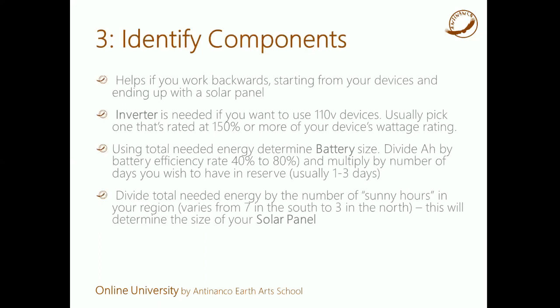Then we're going to figure out how many sunny hours we have in our region, and based on that we'll determine what size solar panel we need. The solar panel is measured in watts, and we can figure that out based on our consumption needs. And lastly, we're going to select the charge controller that will go well with our solar panel.